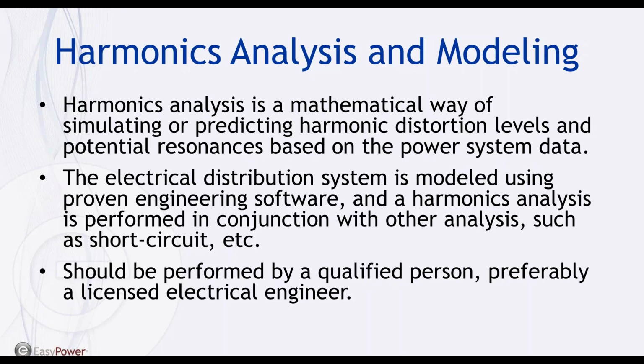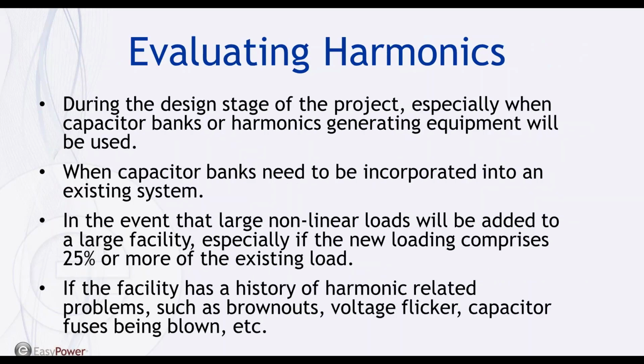It is recommended, definitely should be performed, by a qualified person, preferably a licensed electrical engineer. Also, mitigation methods can be analyzed to determine the effects of adding different types of equipment to limit or eliminate the harmonics. So when should a power distribution system be monitored or evaluated for harmonics?